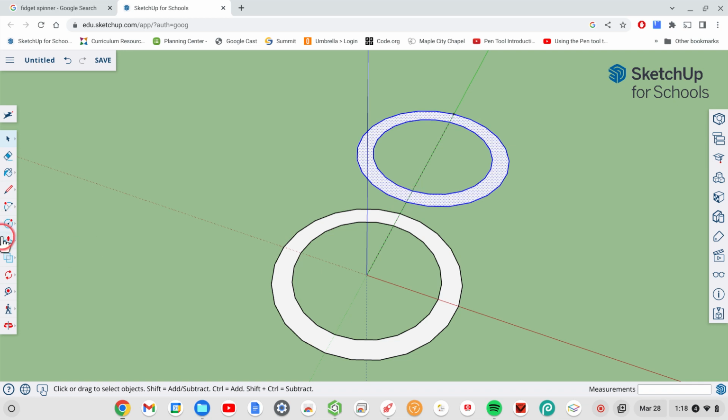So I'm going to go back to that rotate and copy tool. So here's rotate. Make sure I press Control to copy, and then in the instructions it says click to set the center point of rotation. So I'm going to click the point of origin as the center point, and then the next step would be to grab basically anywhere in space and then rotate.